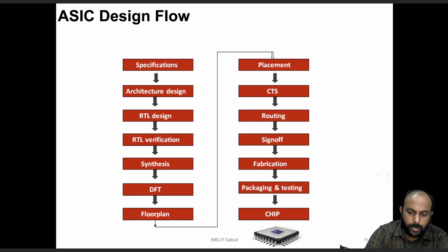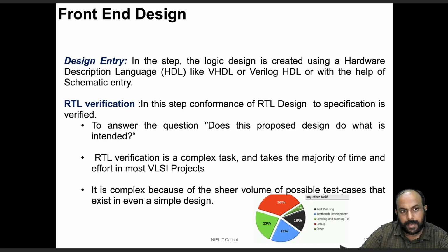Now with this background, let us move on to the basic ASIC design flow. So what you see on the screen is the ASIC design flow, which is kind of generalized, but from design house to design house there could be minor variations in individual steps. If you look at the ASIC design flow, you can classify it into two areas. Basically it's called as a front end as well as a back end design.